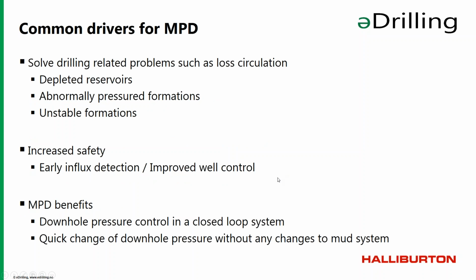Okay, I'll talk a bit about the common drivers for using the managed pressure drilling technique. This can be used to solve drilling related problems, like for instance lost circulation. This can come when you've got depleted reservoirs, abnormally pressured formations and also unstable formations. We also see that MPD is used in reservoirs where you have a tight margin between the pore pressure and the fracture pressure. Using MPD you get increased safety.